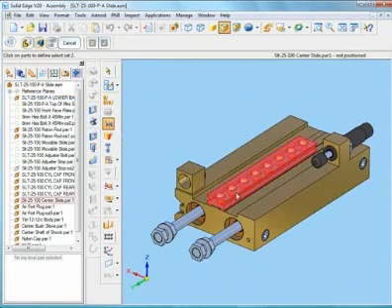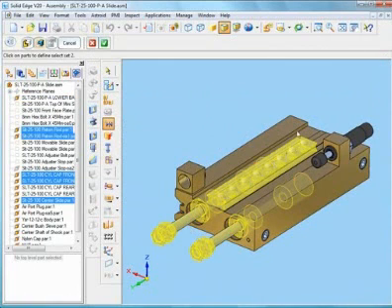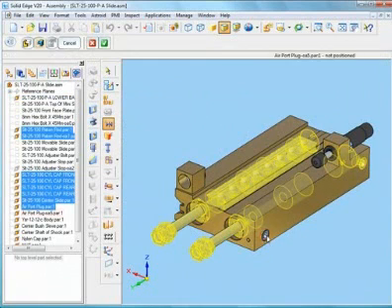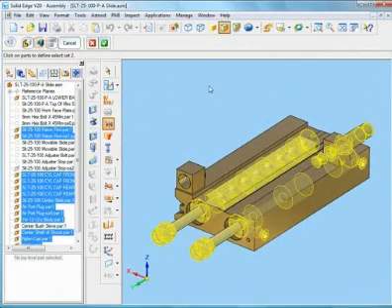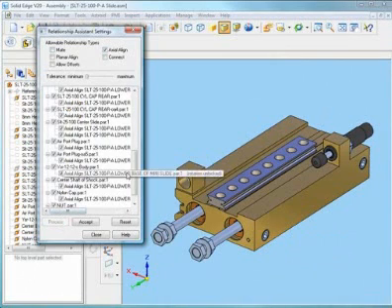Auto-constrain is fully automatic, but to ensure the most control, there are options that allow you to interact with the process. In this example, we chose the option to select one set against a second set. The first select set is the base of the pneumatic slide. The second set will contain all of the remaining parts being selected now.